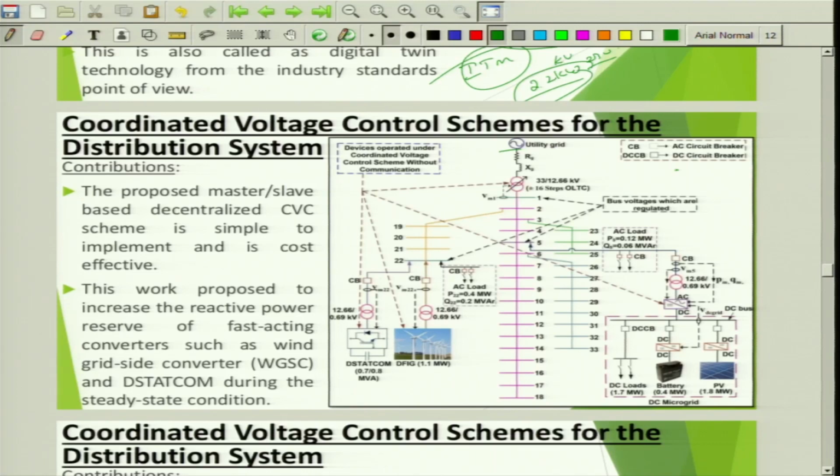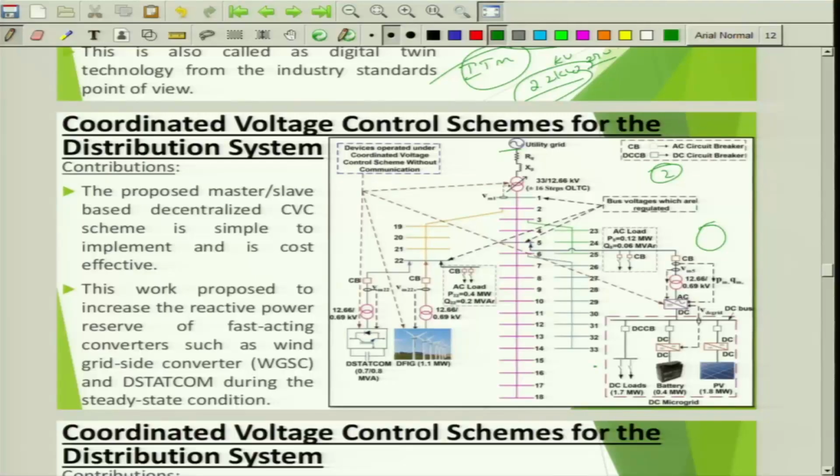You are very familiar with two types of distribution networks: one is the radial network, and there is the mesh network or ring network, right? Though we prefer a mesh network, we often see systems that are radial. In conventional systems everything was radial basically. In the radial system, the biggest disadvantage that one can see is the far away bus.